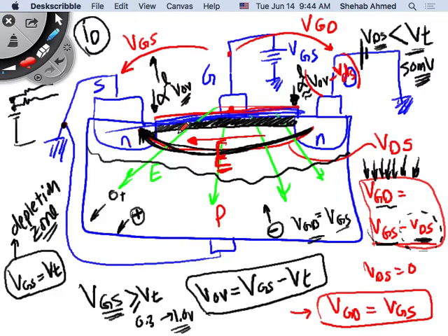Does the thickness decrease, but the amount of electrons stay the same? Not really. The area of the channel will be less, so the amount of electrons in the channel will be less. But something else is happening, because I increase the electric field. The higher this electric field is, the more it will find some more minority electrons around, and the more it will be able to push these electrons through that pinched channel, even though it's very difficult for the electrons to pass through.